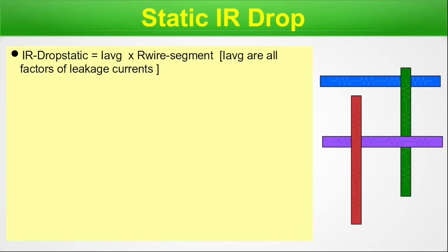Here you can see a simple representation of various metal layers that are going through. If we say the horizontal ones, the first one here could be metal 2, and this could be metal 4. However, you can see inside I have drawn the resistances. Once the parasitic extraction tool extracts any of the metal routes, it will split them into multiple resistors, and they will be connected in either the SPF or the DSPF file like this.